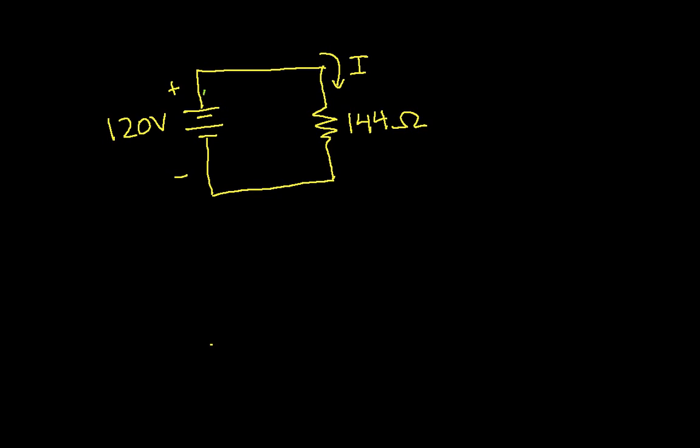So the first is this. This area, or this part of the wire that I'm outlining in green, is all part of one node in the circuit. A node is defined to be basically everything that's connected by just a wire. And because we assume wires are perfectly conducting, there's no voltage difference between any 2 points along this wire. So the voltage here is the same, or there's no voltage drop between here and here.